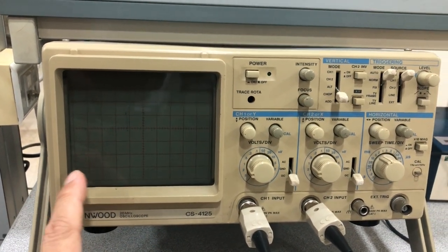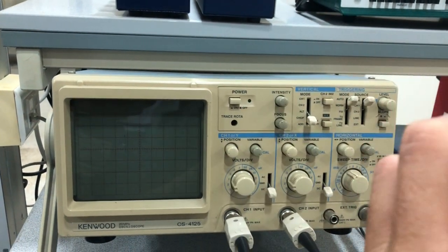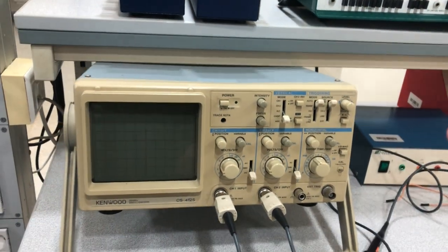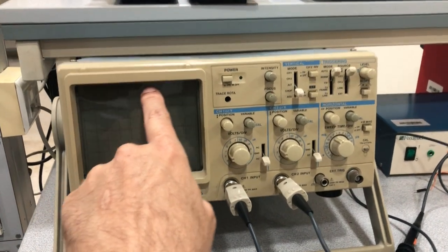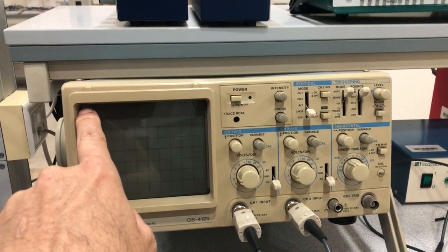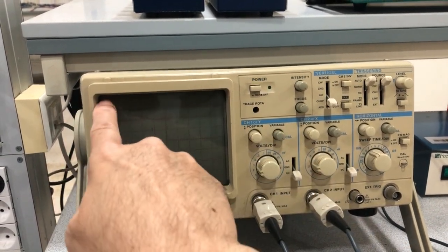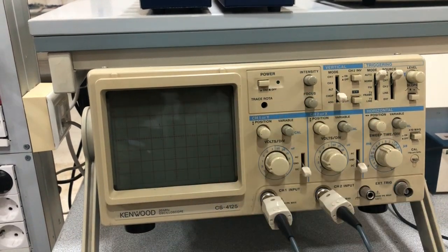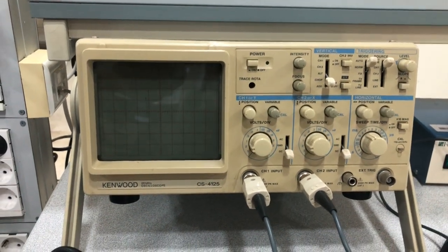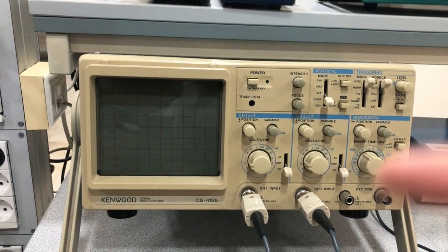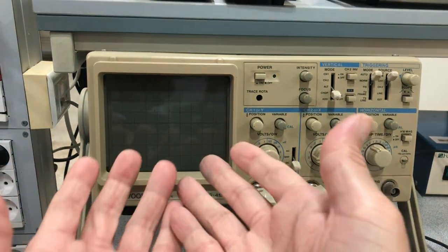Now, for this electron beam, they have coils on the back of the tube. They take the tube and put coils on it, and these coils provide vertical deflection for the beam and horizontal deflection. What they do is control where the beam is going to scan the screen. It starts on the top left corner and goes to my right, then goes down and scans. It plots by basically scanning, but it turns on the beam only when there's something to be displayed. So the coils deflect the beam even though it's turned off, but when you're ready to display a curve or a signal, the electron beam is turned on, and then you see shapes here.